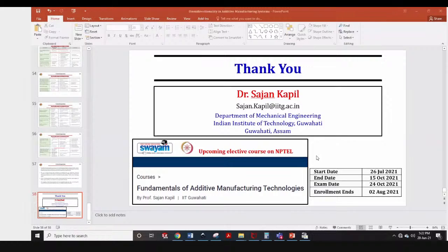And sir, one more thing. I wanted to know the overall motive of getting omnidirectional property in DED. Actually, what is our main motive? To make the component the same at different locations. You move your machine in any direction, you will get the same results. That is the whole goal. Meaning to say, even if you are making an isotropic part, the part you produce at this location should be similar to the part you produce in another direction. Maybe anisotropic, right? But it should be similarly anisotropic.